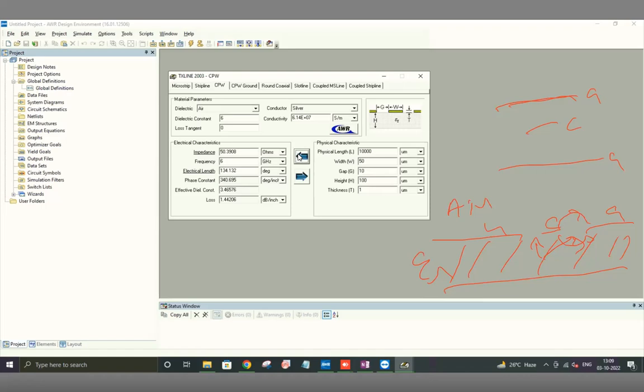But then you can make everything smaller, just like we're talking about the coax, both the center pin and the outside pin becoming smaller. You can make the CPW taper and become very small, with both the center and the gaps being small. And now it can interface with some devices you are doing experiments with. So it's very, very convenient for that aspect as well. But we will discuss this in more detail in the next class. There is one variation. This whole structure is buried in a dielectric. It's on top of a dielectric. So look at the figure here, this figure, right? So the dielectric is at the bottom and the metal is on the top. I have some information.